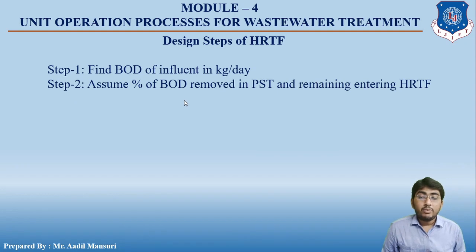Step 2 involves assumption of BOD removed in the primary sedimentation tank and the remaining entering the HRTF. A certain percent of BOD is usually removed in the primary sedimentation tank, right? So the rest of the BOD will enter the trickling filter, so we have to make that assumption.